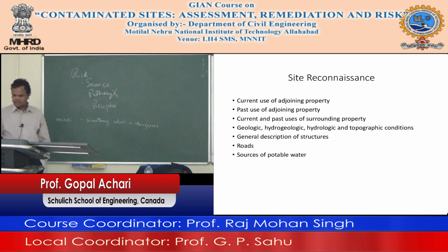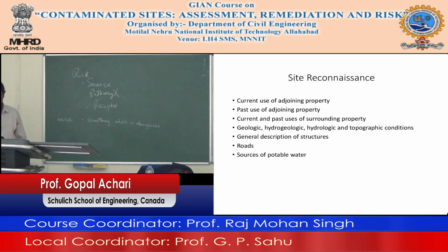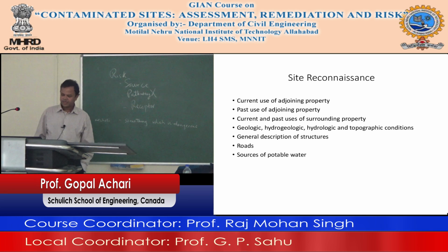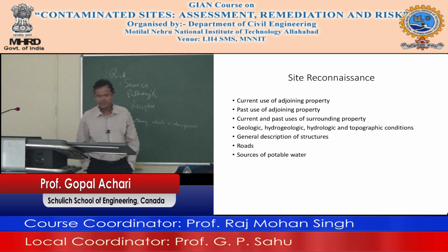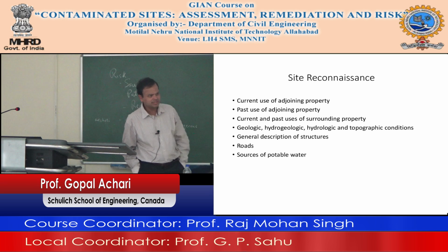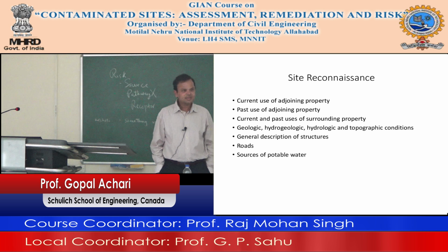Current and past uses: you should look at the geologic, hydrogeologic, hydrologic and topographic conditions. General description of structures. If you see distress in the structure, stains, or if part of it has fallen, why did that part fall? Is that because there was too much load?